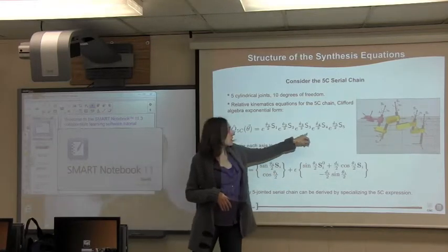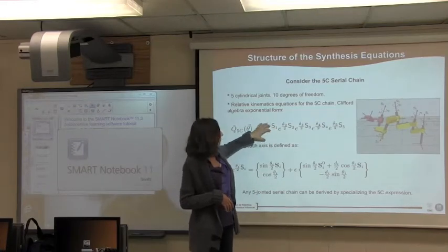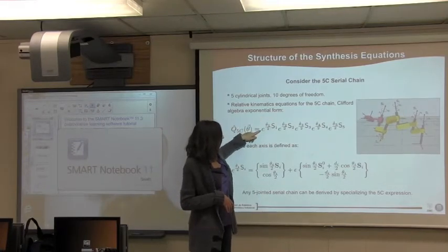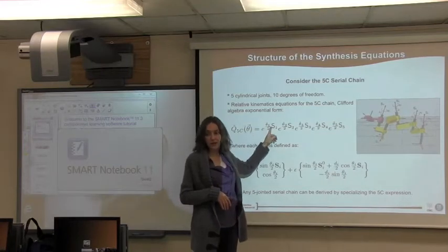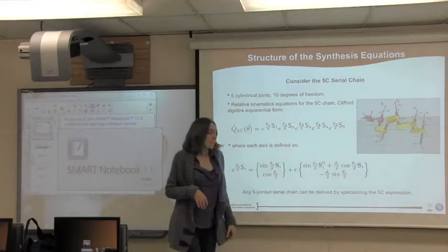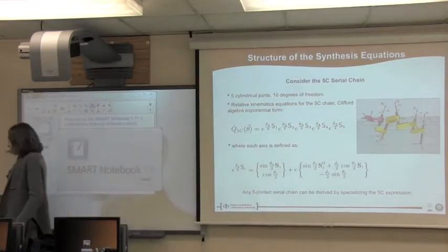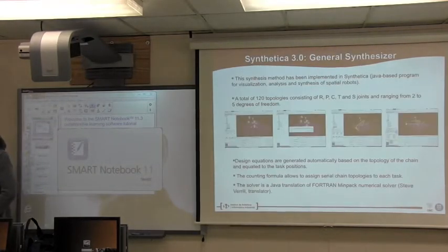So this will be the forward kinematics equations, and this is the exponential notation. This is basically the exponential of the axis times the angle over 2 is a rotation about that axis. And we haven't done this theory, but let's take it as just a notation. Okay. And then you can count the terms, and I was implementing a solver here, so I did a lot of counting.